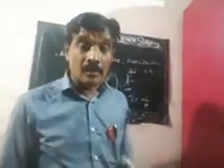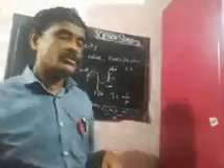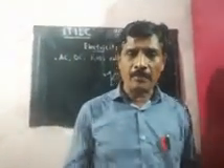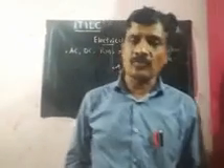That alternating current value is taken as I1 square plus I2 square plus I3 square up to IN square, whole divided by the number of readings, called N, and that becomes the RMS value.